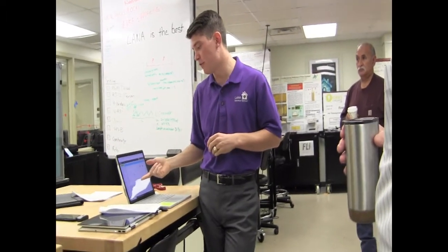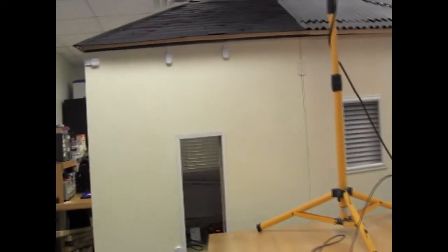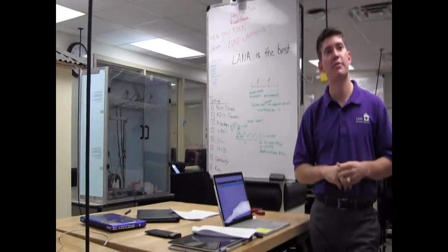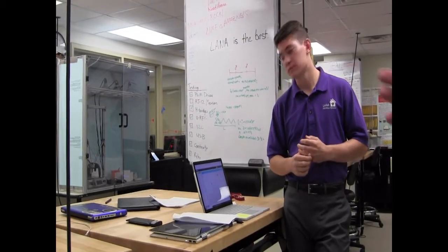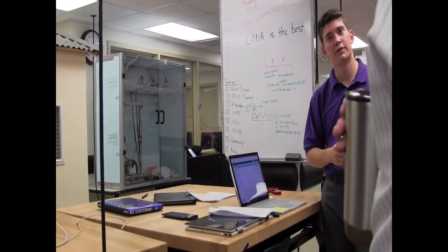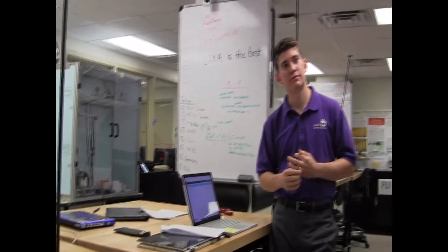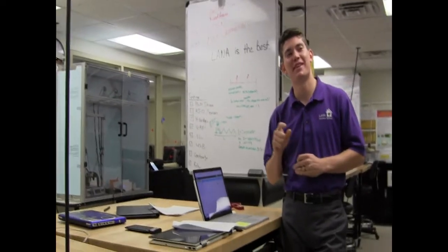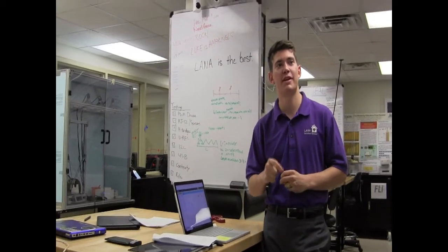So here it's reading 45% relative humidity. And on the inside one I just checked, it was 40. The tolerance range is plus or minus 5%. Okay, and what are you getting? This is 40, that's 45. It's not 5% error. It's 5% relative humidity.